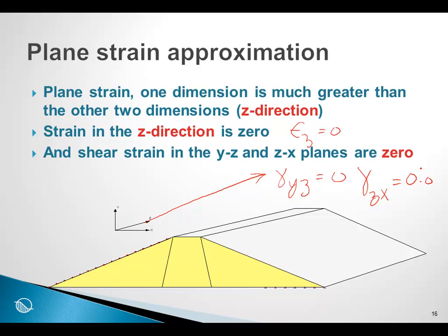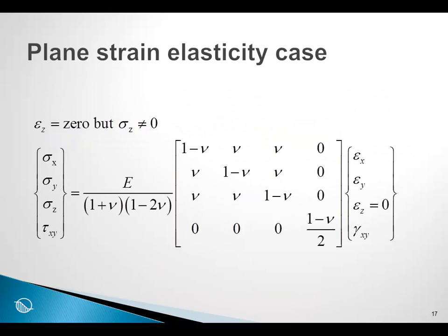So for a plane strain analysis, we are left with this constitutive relationship written in matrix notation, in terms of stress equal to strain. When we write it in matrix notation, the first row of this matrix multiplied times this vector gives us sigma x.